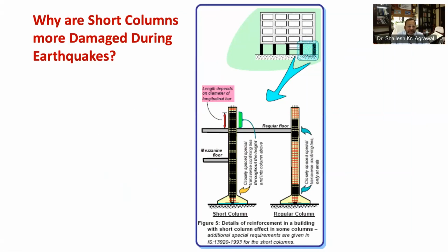As regards new buildings, it is okay, but in existing buildings with short columns, different retrofitting solutions can be employed to avoid damages in future earthquakes. Where walls of partial heights are present, the simplest solution is to close the openings by building a wall of full height, which will eliminate the short column effect. If this is not possible, short columns need to be strengthened using established retrofitting techniques. Being a specialized job, the retrofit solution should be designed by a qualified structural engineer with requisite background.